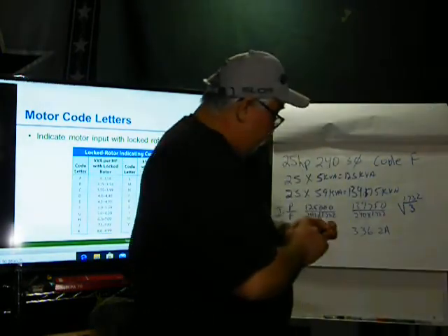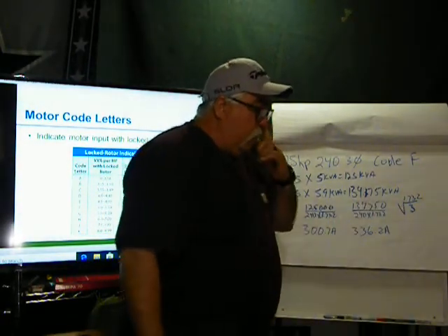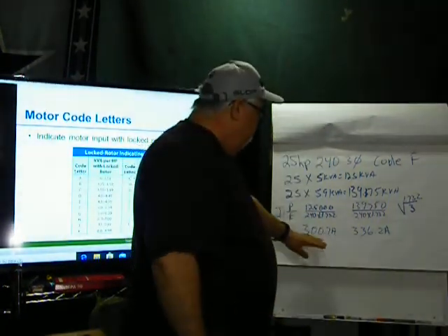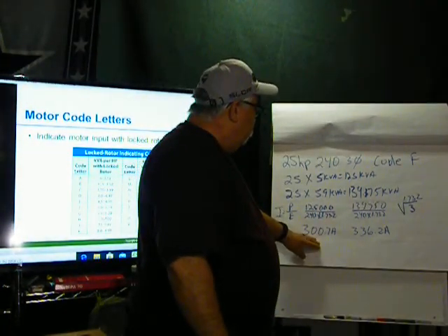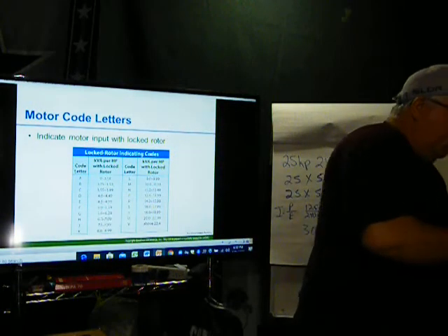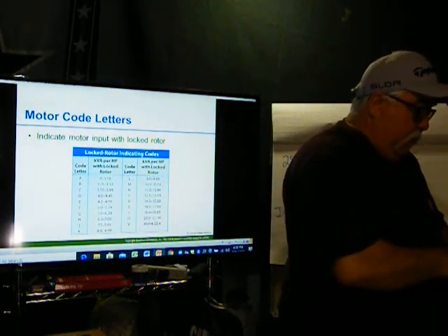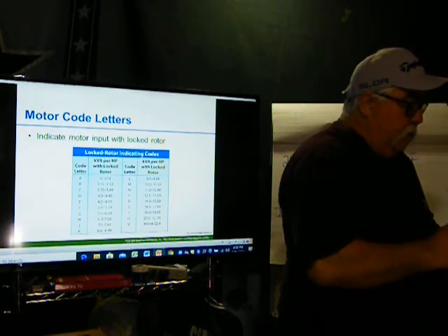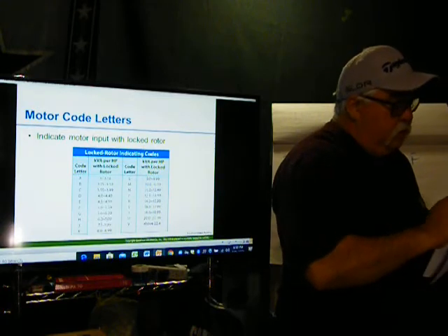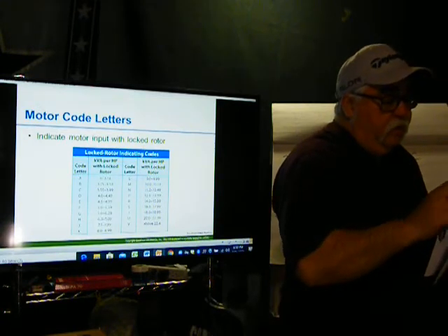Okay? This is the starting current of a motor. So when that motor turns on, it's up to 300 amps. Okay? Up to 300 amps. Let me look at mine. Because I don't have an amperage, I would look at my code to find out more or less what the amperage is on this. So that'd be the 430.250.